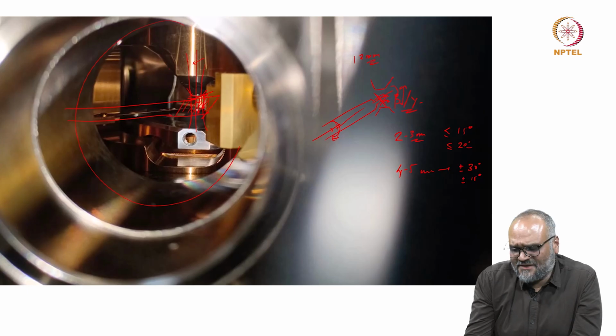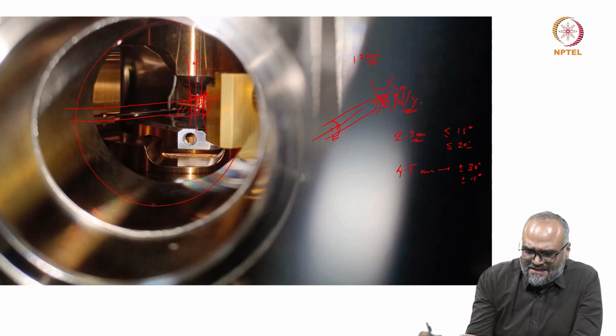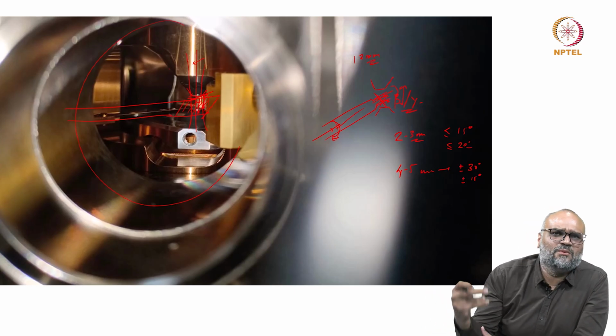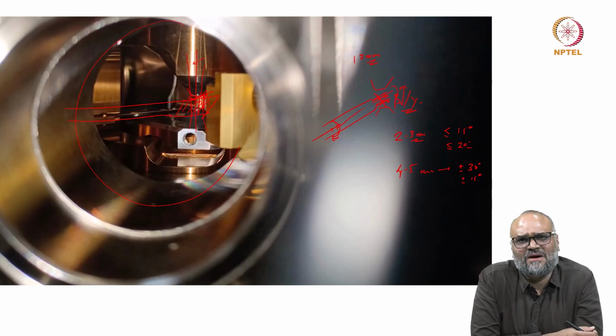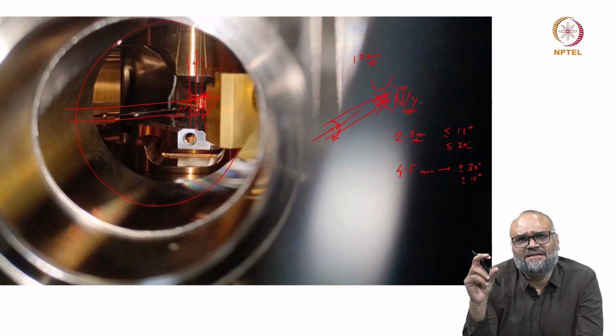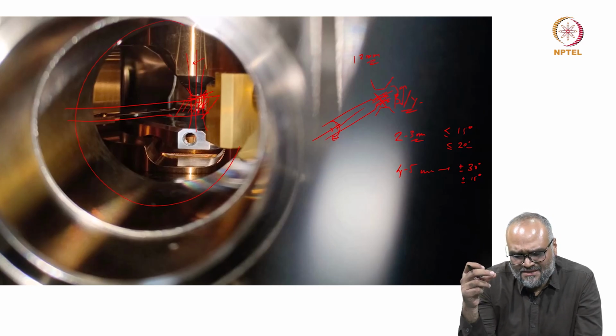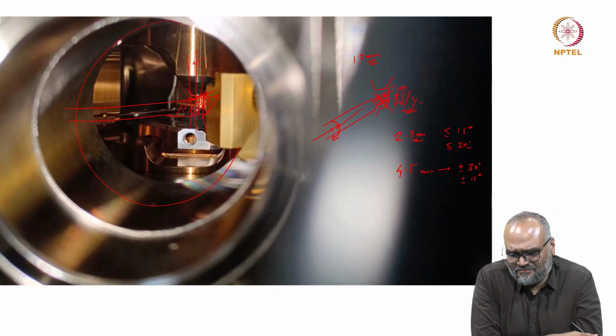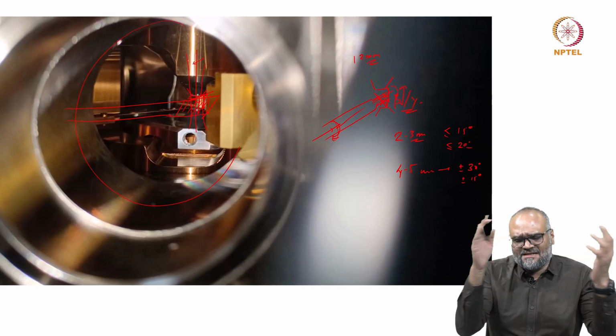There are something called special tomography holders. It is typically at a slightly higher price than the regular holder, which is not always necessary. If you manage to make just the tip of the holder at any local workshop, you might avoid paying an exorbitant sum to just buy a tomography holder. So the idea here is, by restricting the thickness or the width of the holder to a gap less than the pole piece gap of the microscope lenses that you have, you can actually achieve very high tilt and a larger range of tilts.